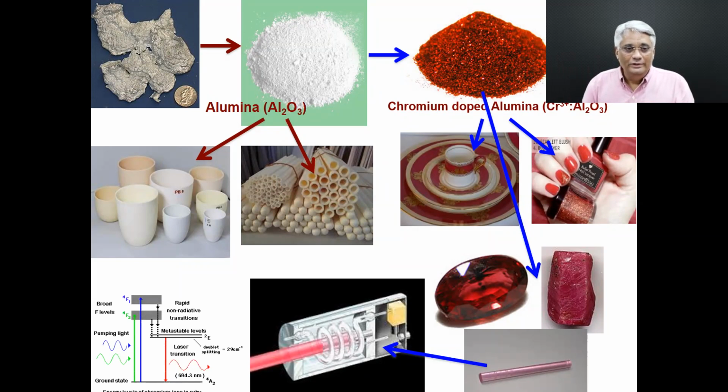So what you do here is, you have this forbidden gap, no? In these wide band gap semiconductors and insulators, the valence and conduction bands are separated by 3 or 4 or more electron volts. But these dopants create special levels.